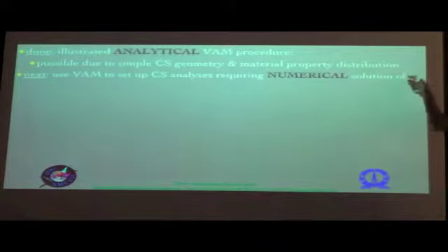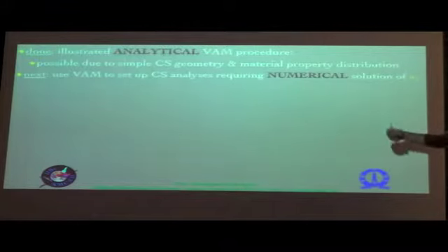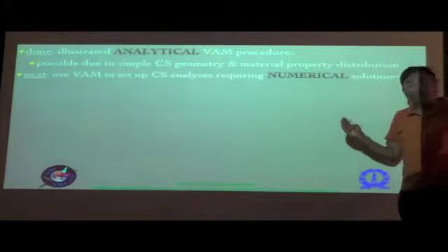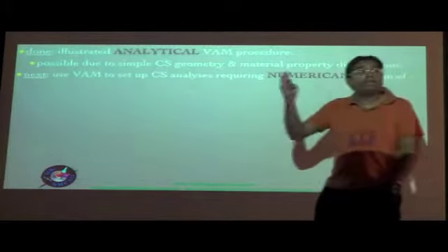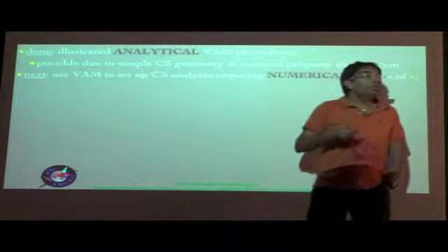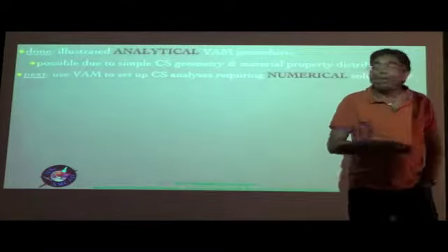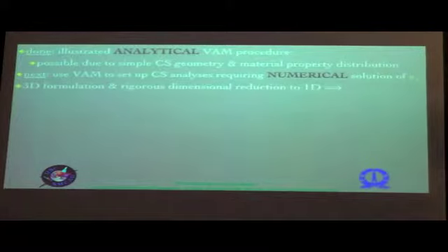Instead, here you still have to solve for Wi, but instead of solving for it in an analytical closed form solution kind of an approach, we would have to resort to numerically discretizing it, and this discretization, as I said, is basically a cross-sectional discretization, and the cross-section is a plane, it's a 2D surface, and therefore you have to involve 2D finite elements in this exercise.